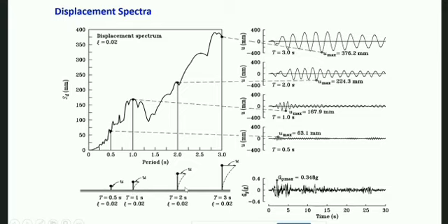And you realize that the stiffness 3EI by L cube will be lower as the stick is longer, so the stiffness of the system will be lower as the period is larger, and therefore it is a more flexible system. Larger period means a more flexible system, and a more flexible system will undergo larger displacement, and that is reflected.